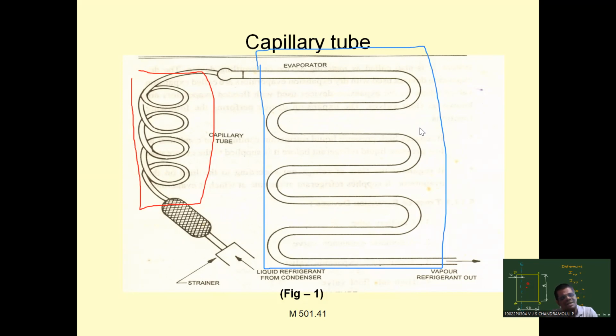We have seen the capillary tube already while doing our project work in the college. It is nothing but a tube having a very small diameter, and the hole in the tube is again of a smaller diameter. The diameter of the hole is further reduced compared to the outside diameter of the tube. Due to the small diameter, it offers resistance to the flow, due to which the pressure is reduced. Let us see one by one.